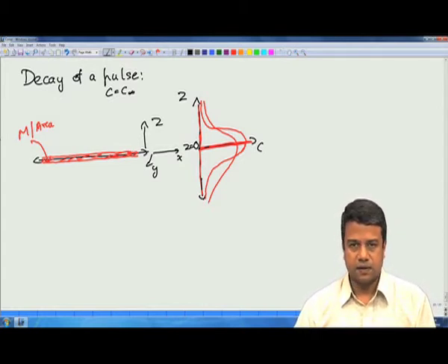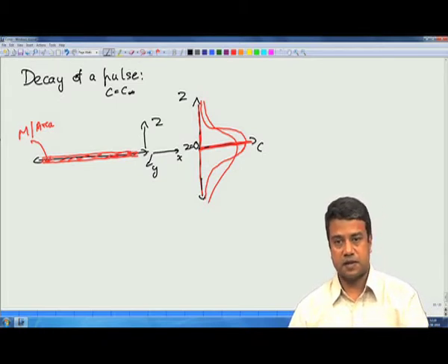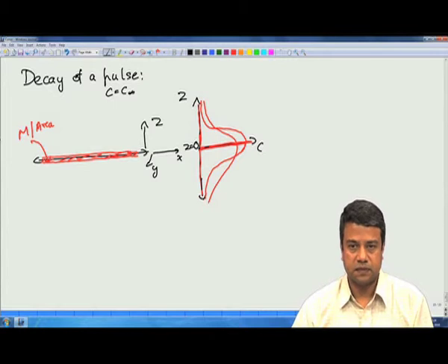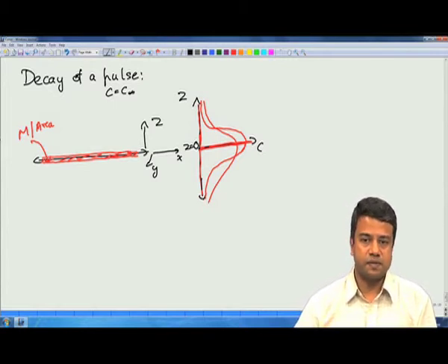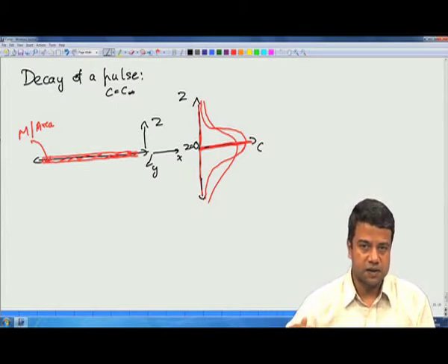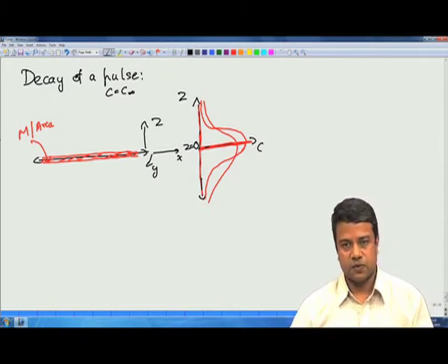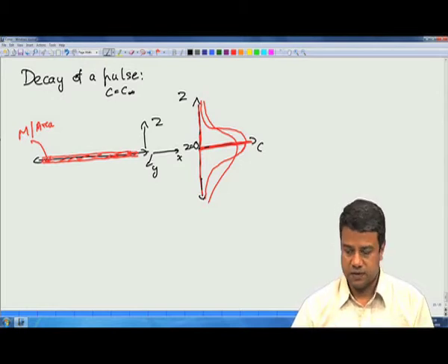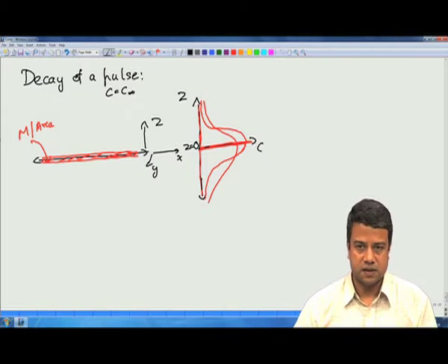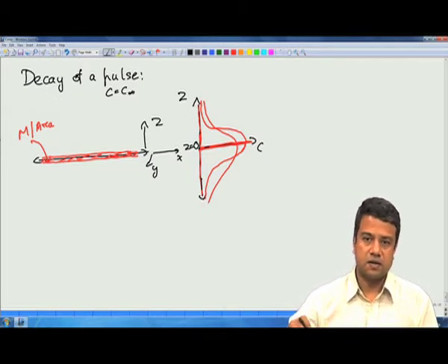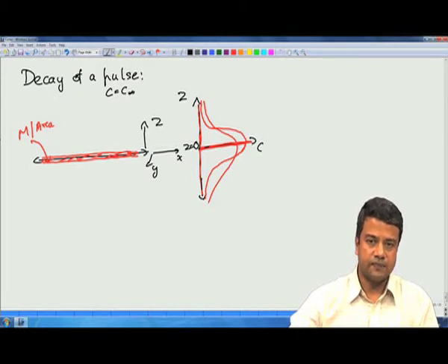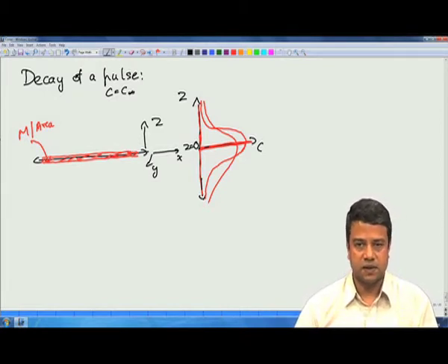I should note that since the total amount of mass is conserved, as it spreads the height has to come down. So, it is not like the previous problem where we had a constant concentration at the surface. In this case the total mass is conserved. So, whatever is put in initially is what is going to diffuse. As time progresses, the width of the concentration profile will increase with time, and the maximum will decrease with time.